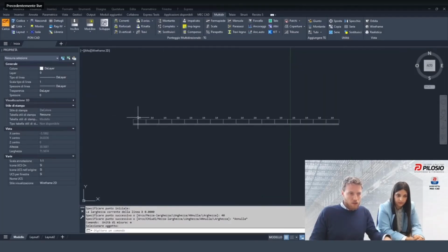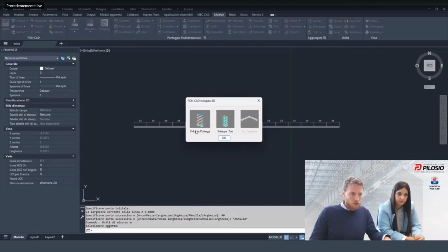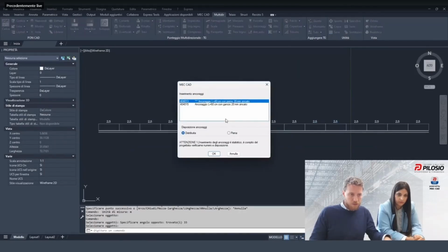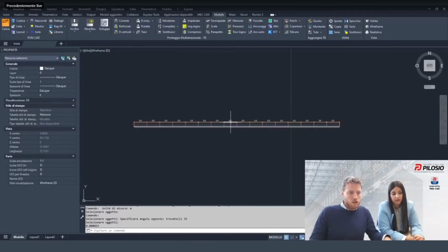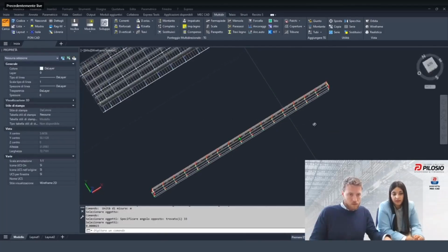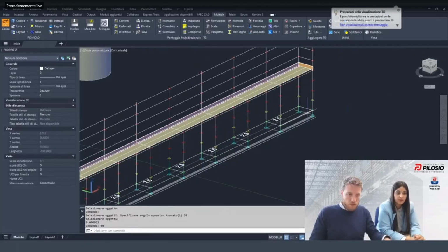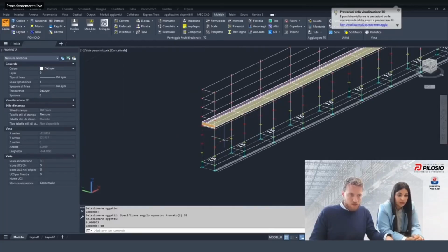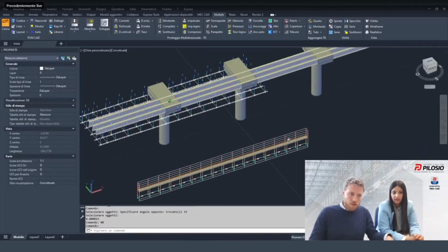Okay. Now PCAD developed the modules, and we have only to make the 3D with this tool. Okay, we will choose the anchors. In this case, we don't need the normal anchor because it's a bridge, and we will use the tie anchor or the anchor on the curb, but it's a default item, and then you can change it later.